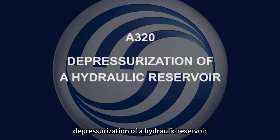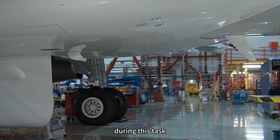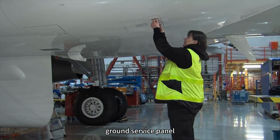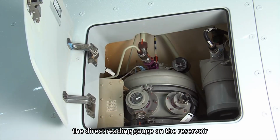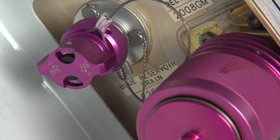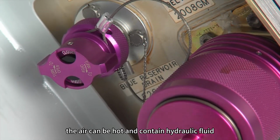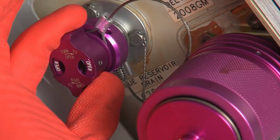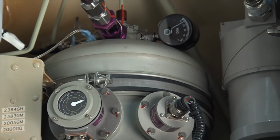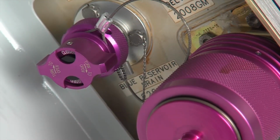Depressurization of a hydraulic reservoir. Make sure the hydraulic system will not be pressurized during this task. Open the access panel to the hydraulic ground service panel. The direct reading gauge on the reservoir will show the actual air pressure inside the reservoir. Wear the proper protection when you open the depressurizing valve. The air can be hot and contain hydraulic fluid. The gauge on the reservoir will show the decrease in pressure. Make sure the valve is completely closed.